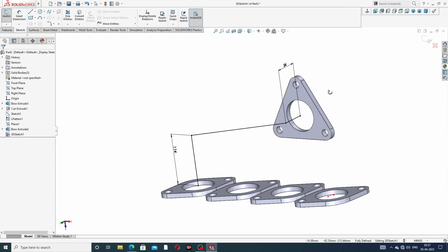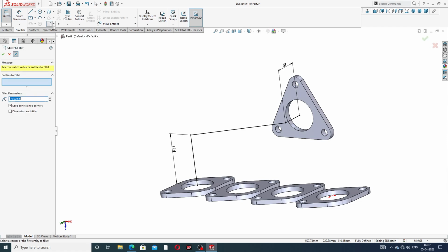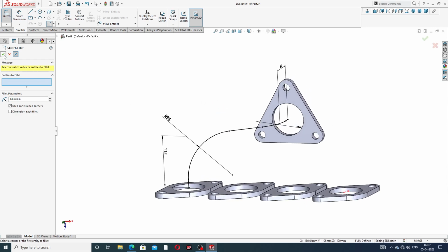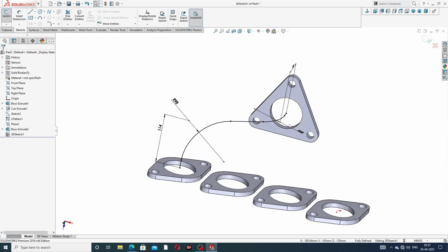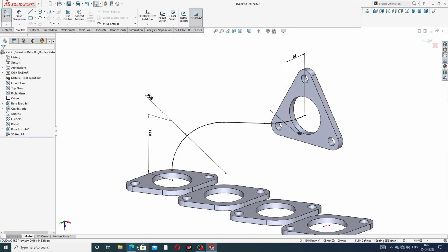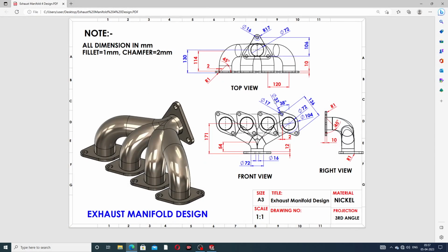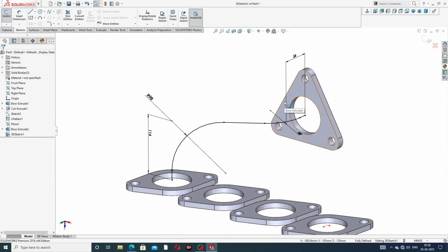And two important points: the fillet command is used with 98 millimeter first, which is this, and second is 68 millimeter, this to this. This is extra, added here because this is a missing point in the drafting. This is not available here.